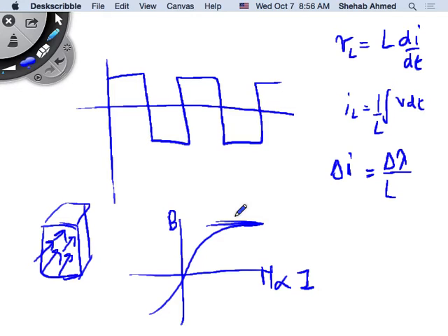So it's like, you push current, you're burning current. You're putting current through the resistance of the windings, and you're just burning I squared R, I squared R, I squared R for no reason. You're not getting any additional magnetic field that you can use to do work. Right? So that's why you stop. I should operate in a place where any increase in current is giving me a good increase in magnetic field, so I can use it to do work. But if I am just pushing current and burning losses, then it's useless.